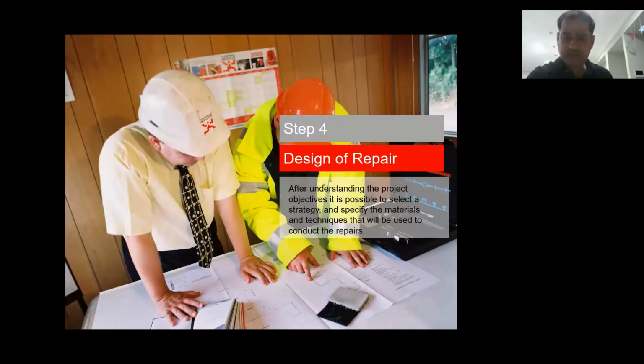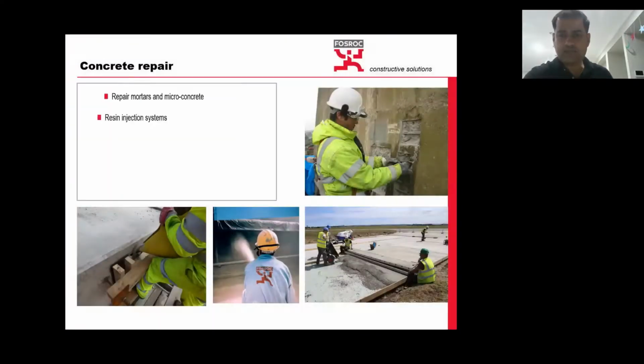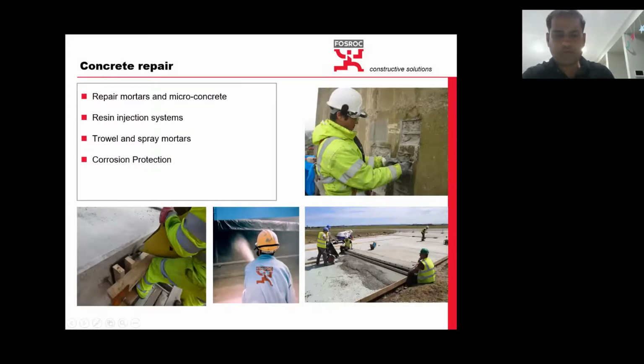When you start talking about the strategy of the repair, the techniques of the repair, you say, okay, let's use hand applied high build mortars. Let's use foam and pour, because this is very important, and you have big gaps of more than 50 millimeter. It goes up to 500 millimeter thick voids. Do we need to demolish it or knock it down? No, you don't need to do that. There are products which are available.